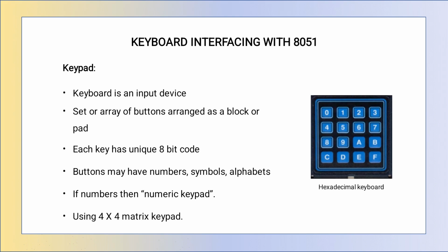Keypad interfacing with the 8051. A keyboard is an input device. It means a set of buttons arranged as a block or pad. If push button keys are used, these keys, when pressed, bounce a few times, closing or opening the contact before providing a steady reading.